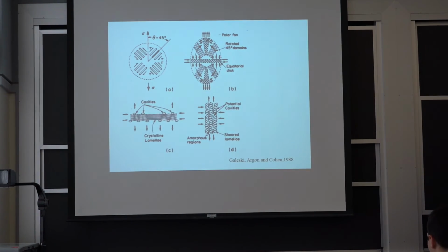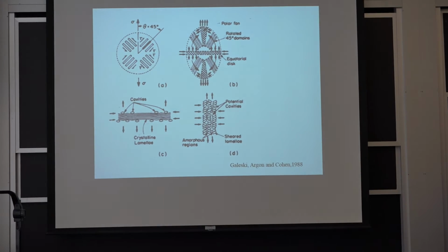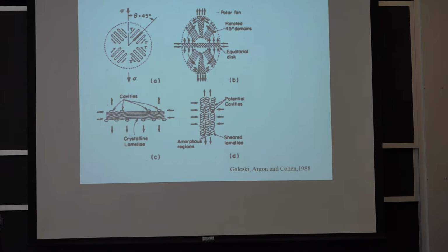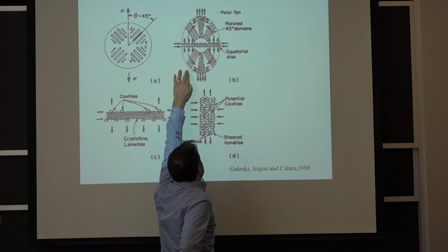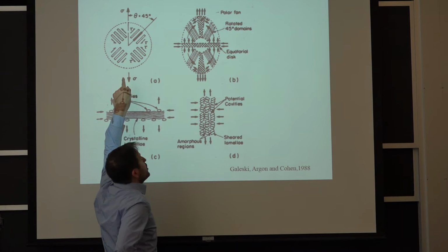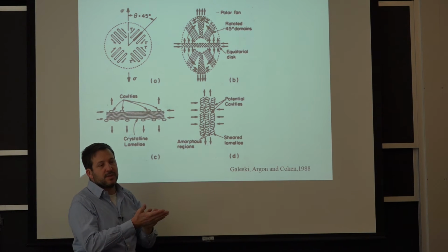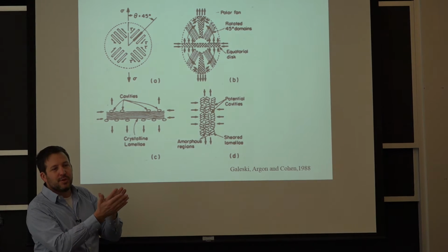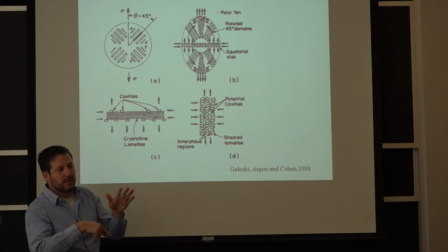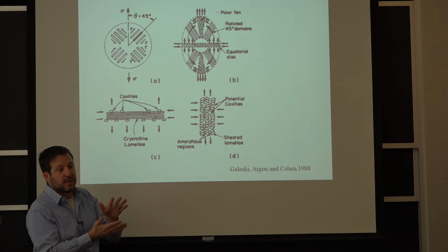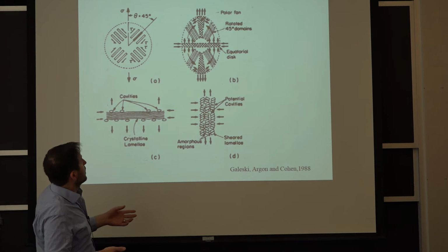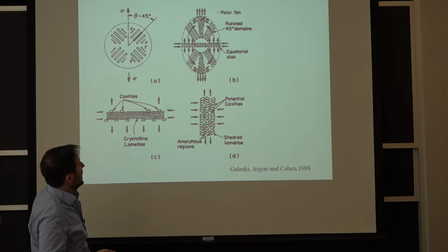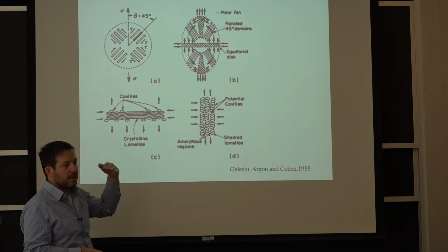Yeah, a little bit. Okay, so we talk about this spherulite and a little bit what's going on in it. There's a lot of transformation taking place. So at the beginning, you start deforming in these shear planes at 45 degrees because you can essentially just be sliding two layers of crystal by deforming the soft amorphous layer between them. Now, you don't have compatibility when you're doing that. You are creating a little bit of tension right at the center.